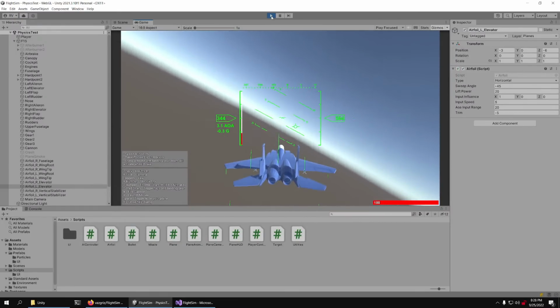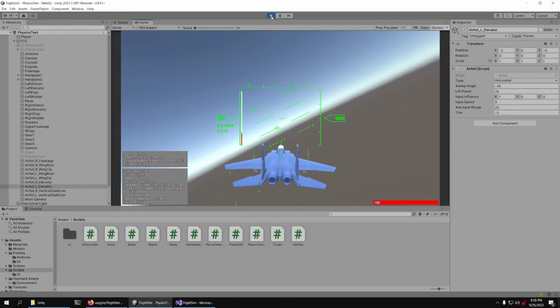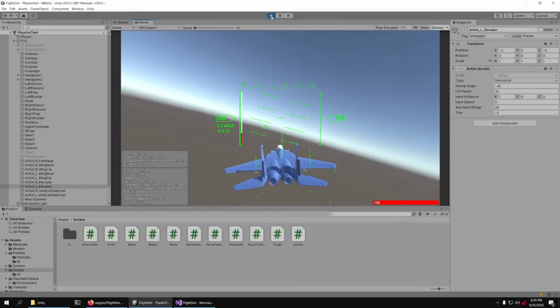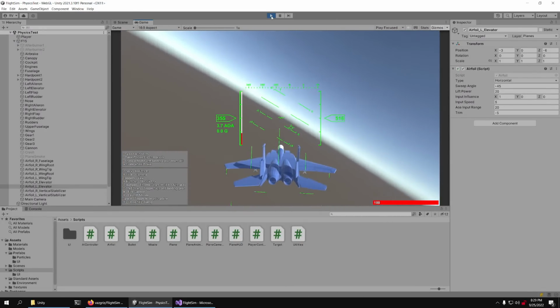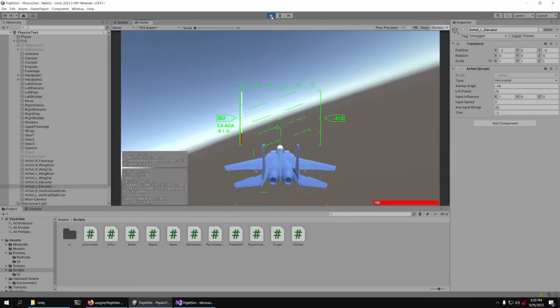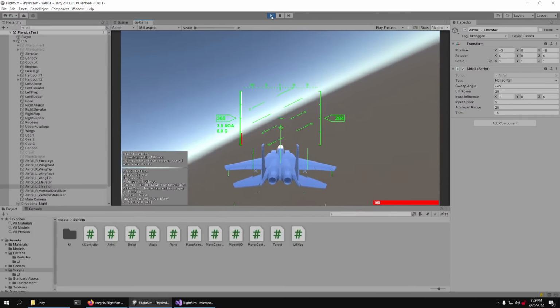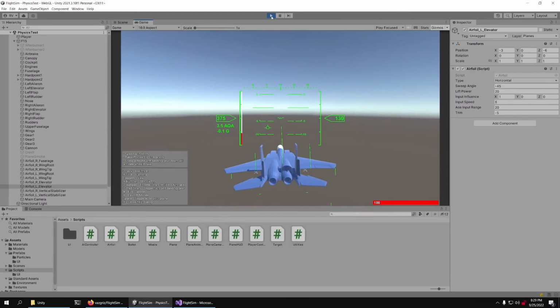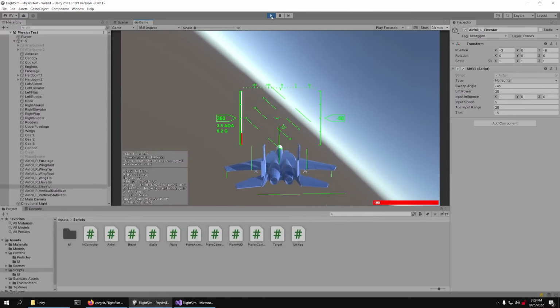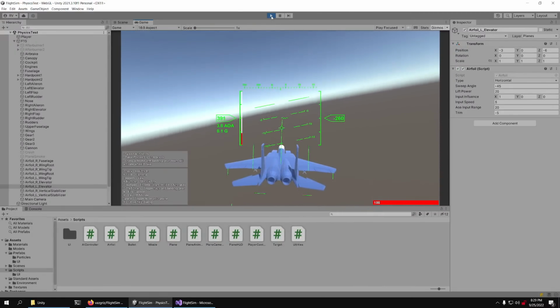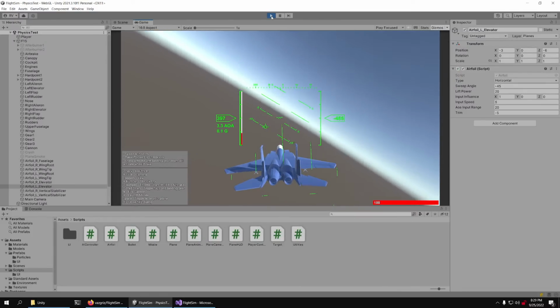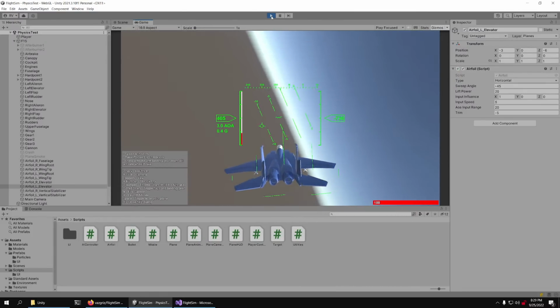Okay, so now rudder input is producing a slight roll input, but in the complete opposite way from what I was expecting. So wait, if I rudder right, that should make the left wing produce even more lift, but it's doing the opposite. The right wing is getting more lift.